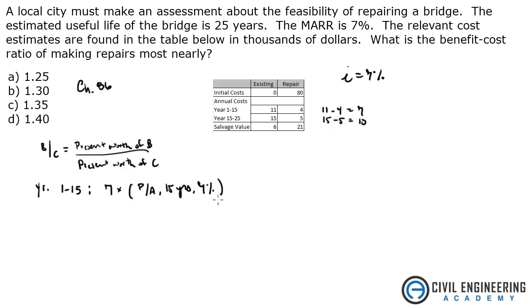If you don't remember what I'm doing here, basically I'm using this to go look up in the interest tables, which are found in the Civil Engineering Reference Manual. Table A-154 is what I'm going to be using for 7% interest. And that's going to give me a value that I can multiply this by. Normally you draw these out on little charts like this.